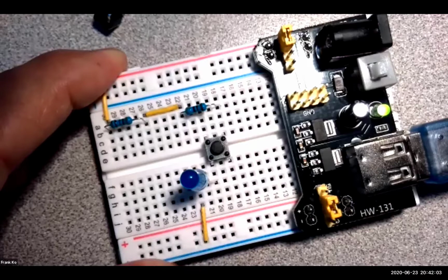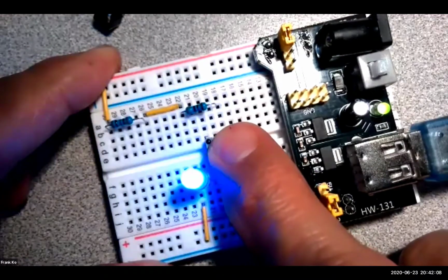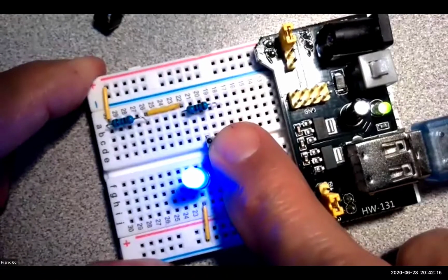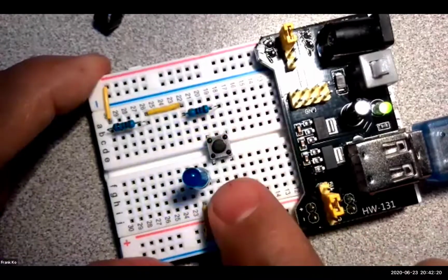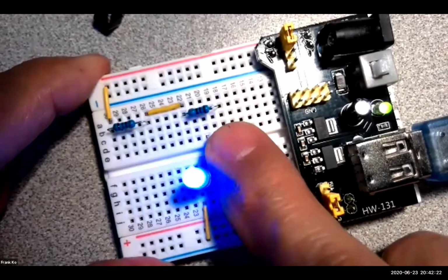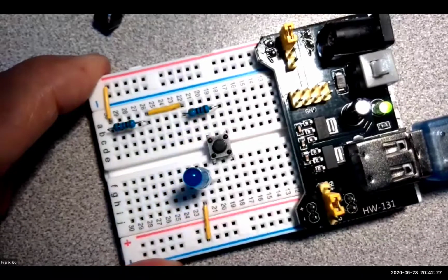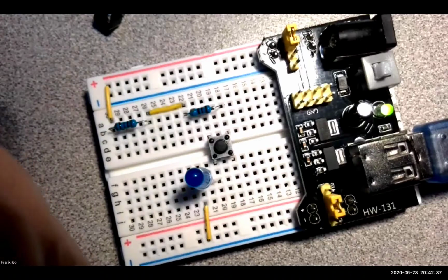Now, to check the circuit for its functionality, if I touch this button now, does my blue light light up? Yes, it does. That means I have continuity, yes? I have continuity from the positive rail through the 2 resistors, all the way through the switch, through the LED. And the LED is here only to let us know that, yes, the circuit is built properly, okay? Once the circuit is verified to be built properly, we want to remove the LED.